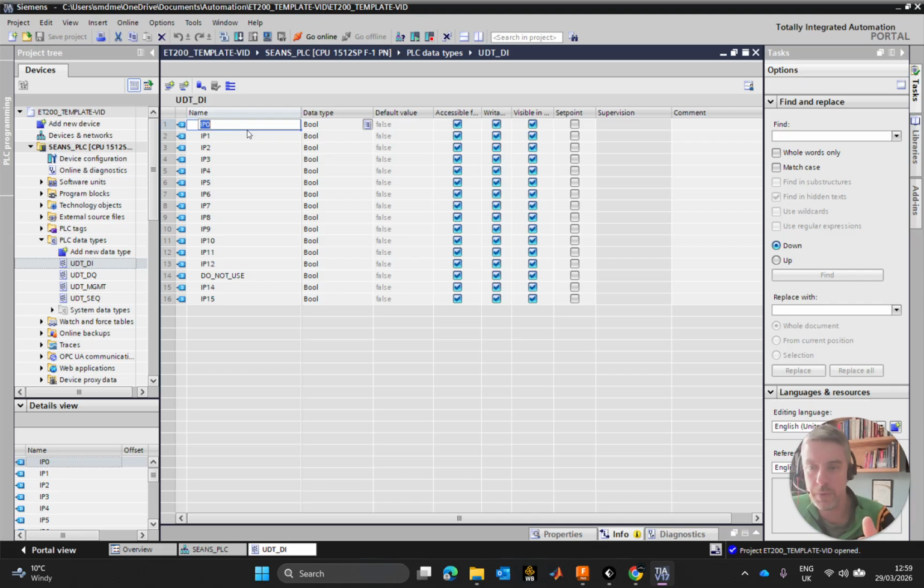So the way I do this is that I'm dealing with two digital input cards, input card 0 and input card 1. Input card 0 has 8 pins, so it is 8 bits, and what I put onto input card 0 is typically going to be inputs from devices located down on the Festo profile plate upon which we mount our cylinders and our equipment.